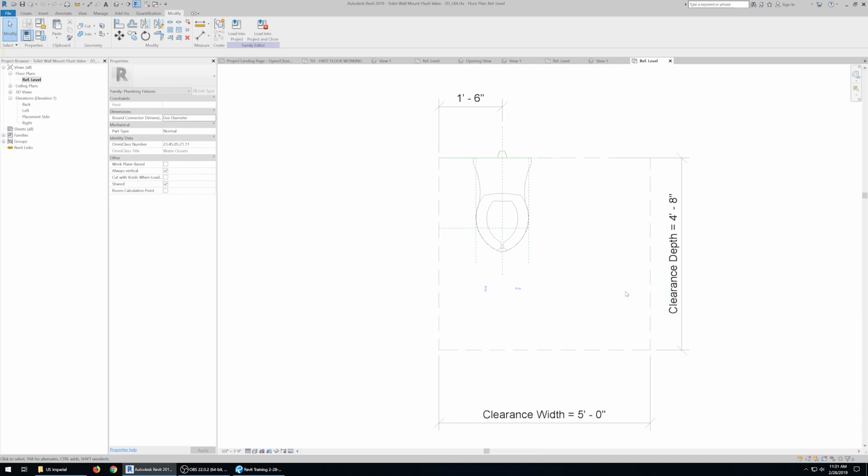So the reason we're doing it that way is to save processing space, so that you don't model a 3D object and then Revit has to do the math on that 3D object every time it repaints. Correct. But now it's doing the math on the lines. Correct. It's still faster to do it 2D. Correct. It's faster to do it this way, and here's why.